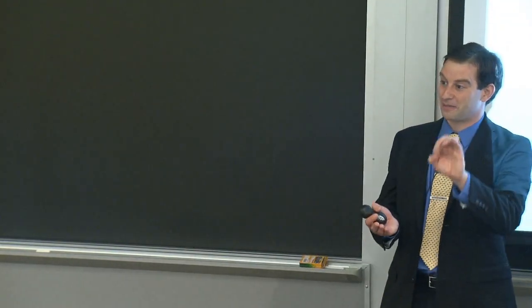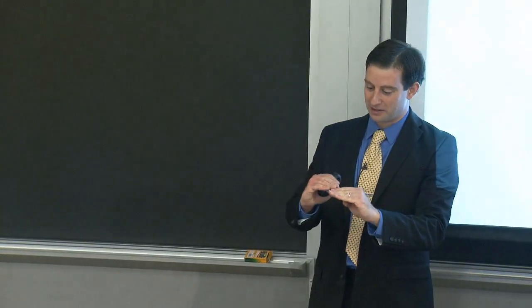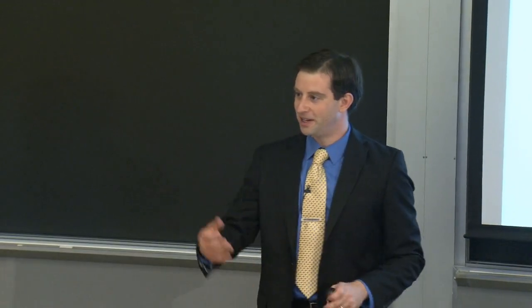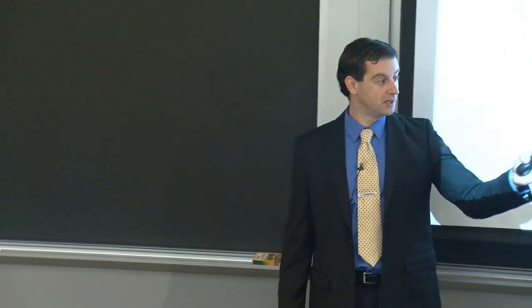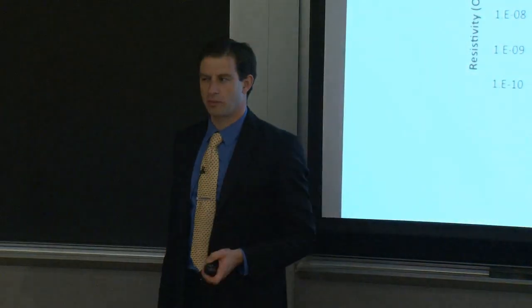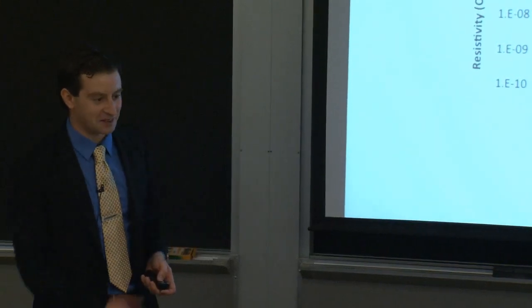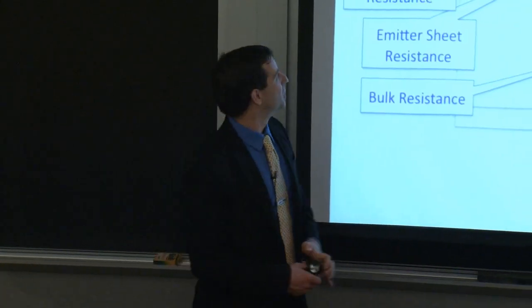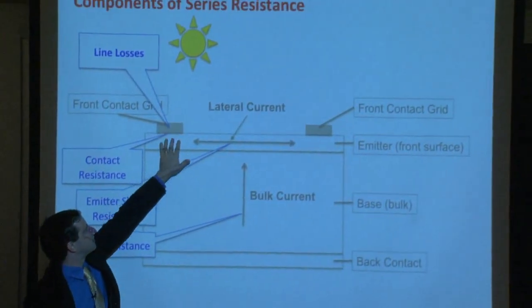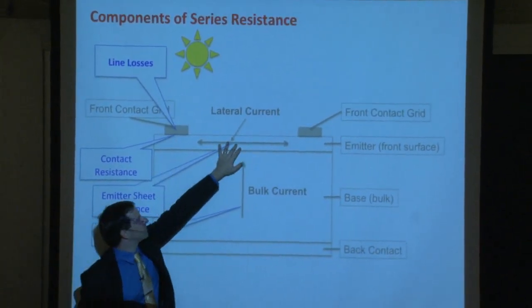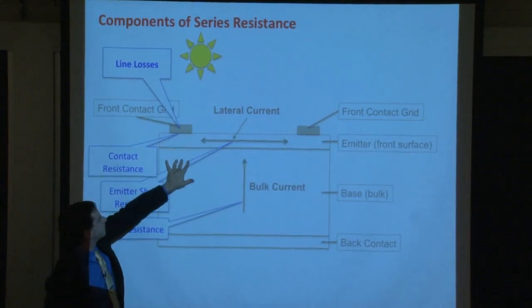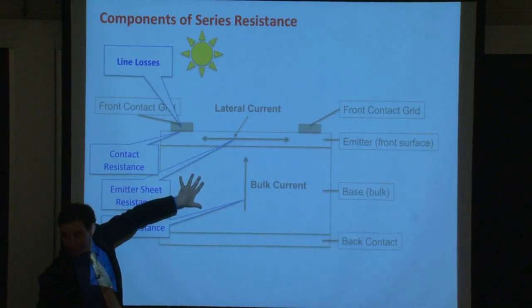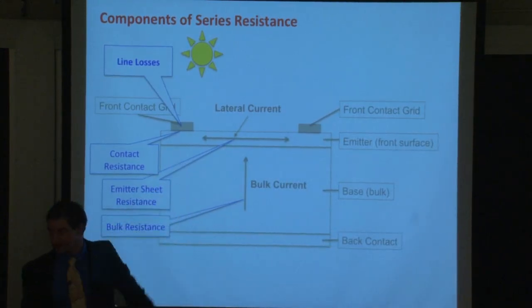So when you fire your contact metallization, when you create the contact between your metal and your semiconductor underneath, you run the risk of having atoms diffuse into your device and hurting the efficiency, hurting the ability of the solar cell to collect carriers. We'll hear more about that on Tuesday. So it becomes an impurity? Yeah, exactly. It becomes an impurity, in this case, unintentional. So just remember where the contact is right here in the emitter. If it diffuses into the emitter, it's okay. The electrons at this point are the majority carriers. But if the metal diffuses all the way into the bulk, the electrons inside of the bulk are minority carriers. And they can be impacted by the presence of that copper there.